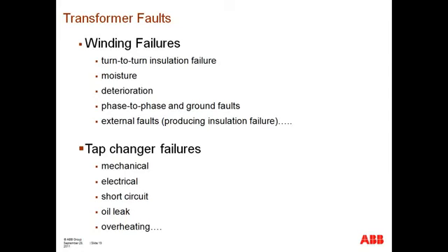Okay. Think of some of these failures as the result of the following. Some of the insulation in these transformers could be in the form of some sort of varnish or some sort of resin. And as you could picture, any of this varnish or resin type components are, relatively speaking, brittle, or they become brittle over time. So when through faults occur, or when the transformer is stressed, there's not only electrical effects, but there's also physical movement because of the magnetic forces that are involved with high levels of current.